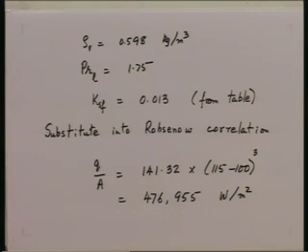Notice the steep increase in the value of Q by A when T w minus T s has gone up from 1 to about 15. We have gone up by an enormous factor. Earlier the Q by A in natural convection was only about 1000, now it is 476,000.